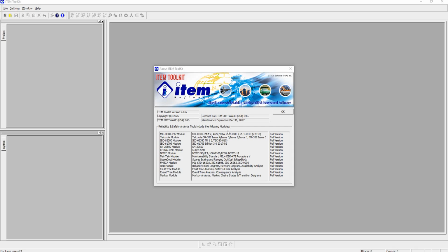We assigned failure effects to the next level and all the way to the system level, and finally we assigned severities to our system failure modes or system end effects. We also looked at completing our data entry for the IEC-61508 by assigning diagnostic tests and assigning our system modes to safe or dangerous failure.